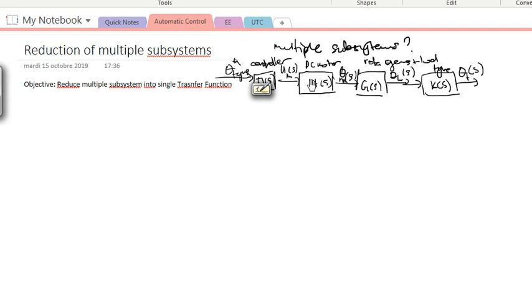So we have seen that there is open loop control and closed loop control. Usually what happens is you wish for some theta tire, but at the end you get friction or disturbance, for example wind speed, or probably friction variation between the tires and the road. So theta T here could be different from the theta tire that you wish for.